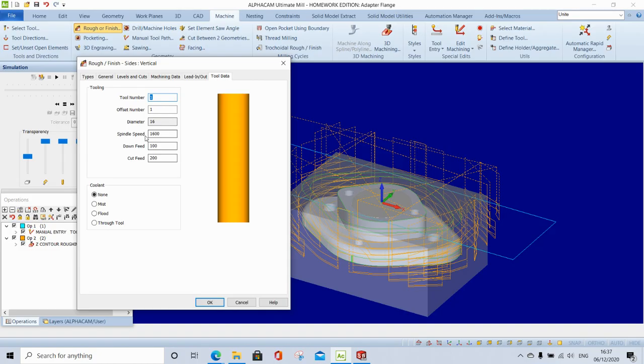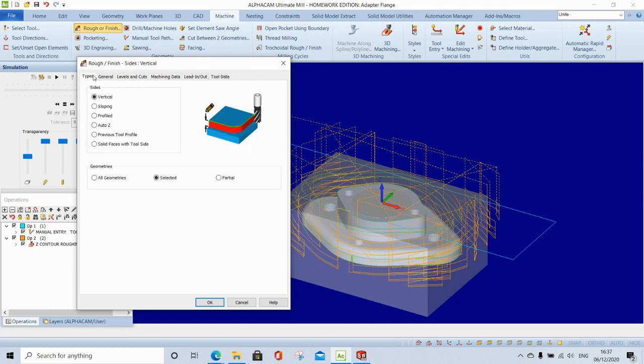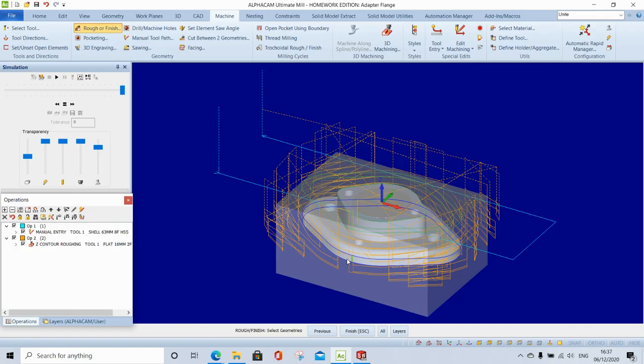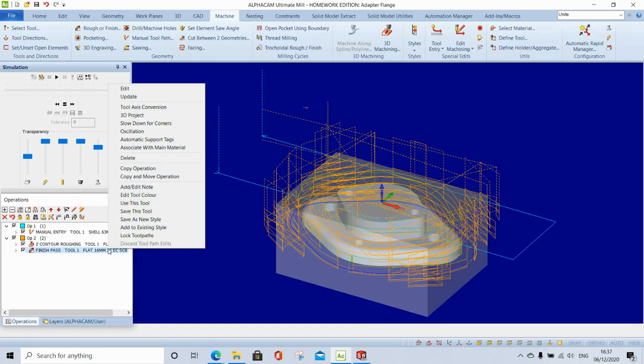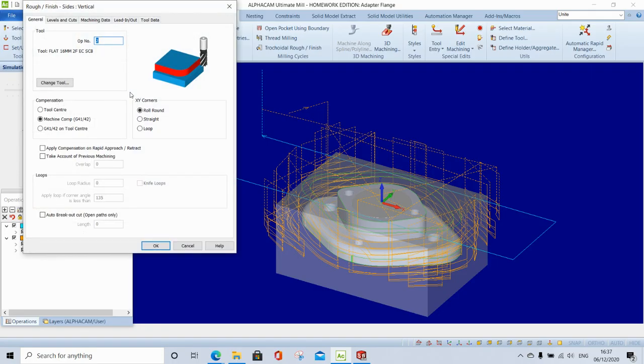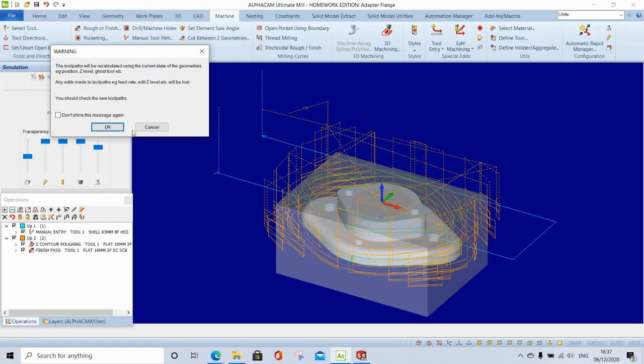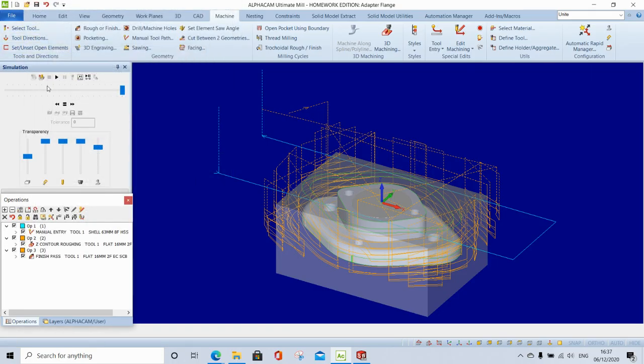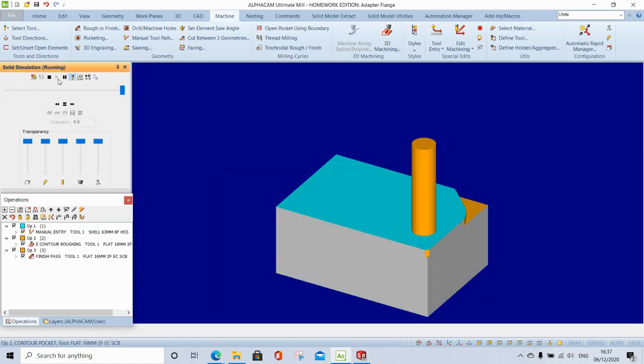Now we should be changing this, so remember to do that whenever you're updating. I'm just doing this quickly, but you should look at the tool sheet, the tool list, and add speeds and feeds as to what it states on the list. Okay, so click OK and then select that. Now I need to just change this to operation 3. Okay, so see what that looks like.